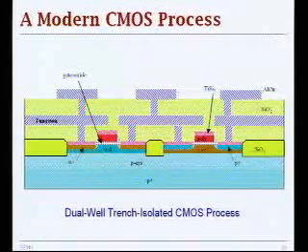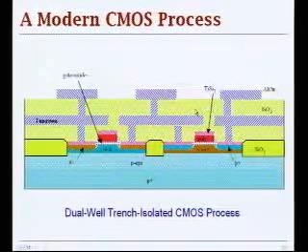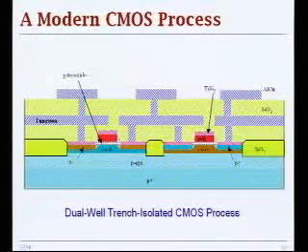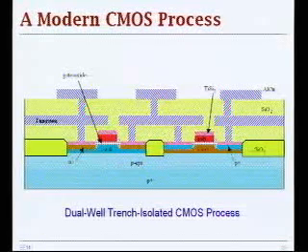And really, starting from here, you can stack all the way up vertically to 7 metal layers today in 90 nanometer CMOS, where your transistors look really tiny and there's a huge skyscraper on top of it. It's really like a foundation. It's quite amazing how these things work.